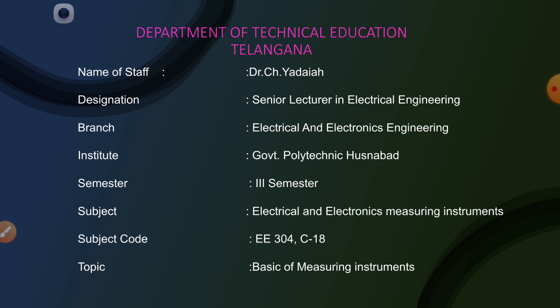What are the torques in an instrument? The torques are classified into deflecting torque, controlling torque and damping torque. The deflecting torque is required to operate the instrument. Controlling torque is required for restoration of the pointer, and damping torque is required to nullify the oscillations at the final position.